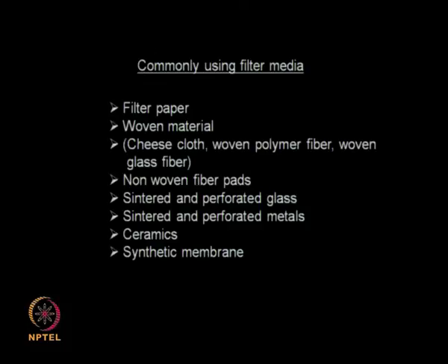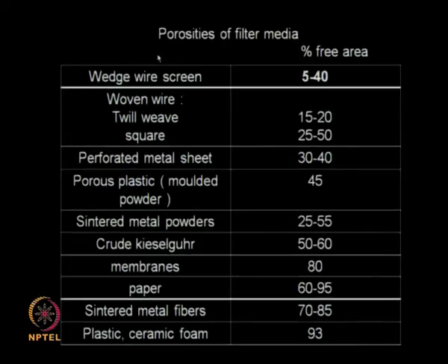Some of them are very inert, they can withstand very high temperature, they can take in abrasive materials, they are long lasting, some of them are short lasting, so you need to replace these filter media. So the cost of your filtration, the working capital I would say, depends on how many times in a year or month you replace this filter medium. So look at the porosities of these filter medium. It varies from almost 5 going up to 85% free area available actually.